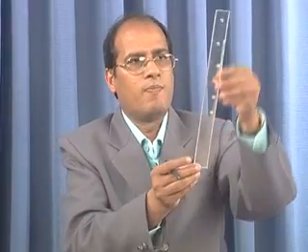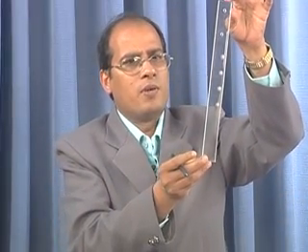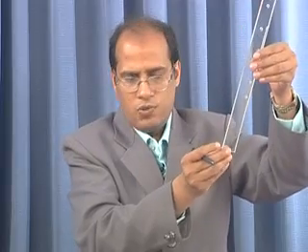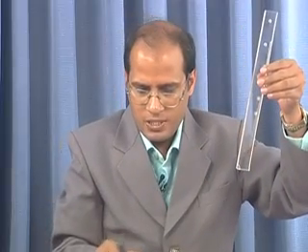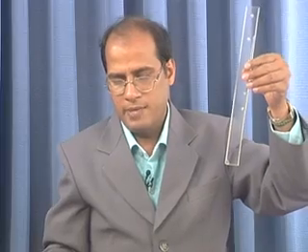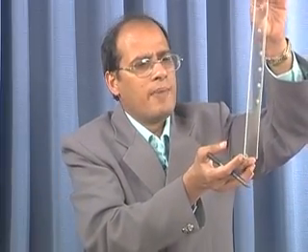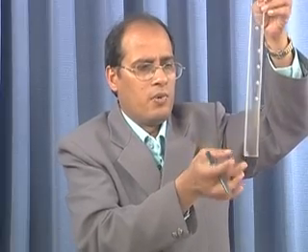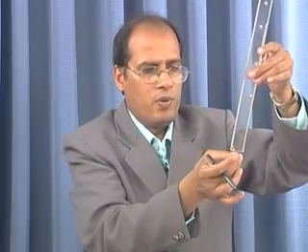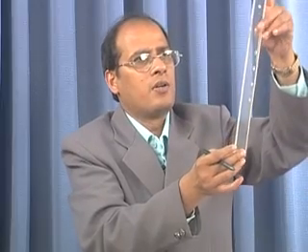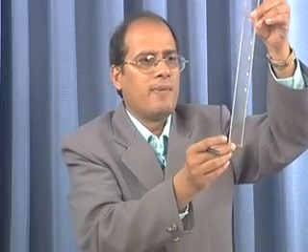And as you know, this u can be written in terms of phi(x) and q(t). So for all times to come, strain at these two ends will be equal to 0. So you can find this expression of the mode shape like this, a sin(omega by c L) equal to 0. If I make a equal to 0, then there will be no vibration of this rod. But as the rod is vibrating, we are studying the vibration of this rod, so a cannot be equal to 0.